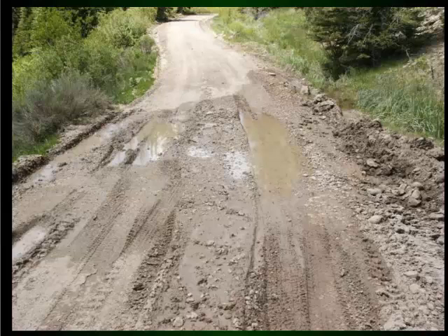What happens in a situation like that is, I don't need to diagram it, with the mud that you saw there. What happens is if you just throw some 3/4 minus over it and then drive over it, repeated trips, it starts pumping that mud up, and that mud will come right up and come over the top of your rock. The filter cloth, geotextile, is a fabric that allows water to go through, but not sediment. So you put that down and put your rock over it, and the fines can't pump up and contaminate your rock. Basically, it makes your surface rock worthless because you get a layer of mud over the top of it.